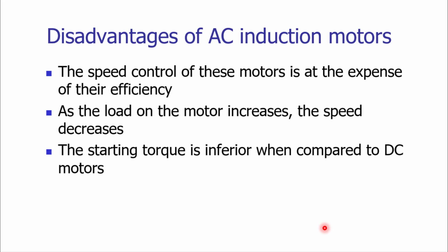If you increase the load on the motor, the speed will reduce. That is the limitation of the AC induction motor. The starting torque which is provided by the AC induction motor is less as compared to the DC motor.